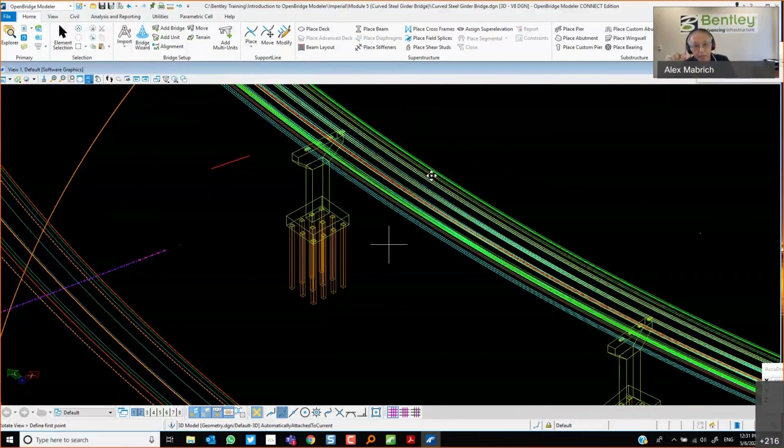If it's the entire deck, because it's the wearing surface, then maybe the best way will be a deck on top of the deck. Now, the question is where you measure your deck elevations. Or do you need to lower the actual deck to accommodate for the inches of asphalt that you're going to place as the wearing surface?